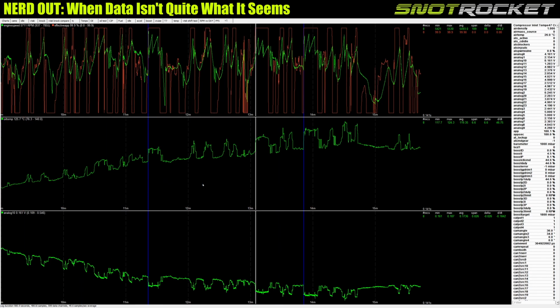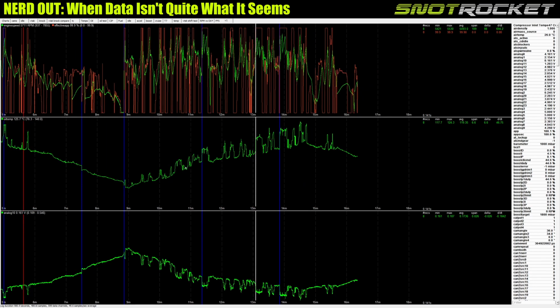Ultimately, if we take the VTEC off of this chart, if we assume that each of these peaks is wrong, the oil temperature is really following this path here. The low part between each of these peaks is actually the true oil temperature. Now what we could do is strip data from these logs where VTEC is enabled, take that out, look at data where VTEC is off, and then look at what that curve looks like, which just for interest I did separately.